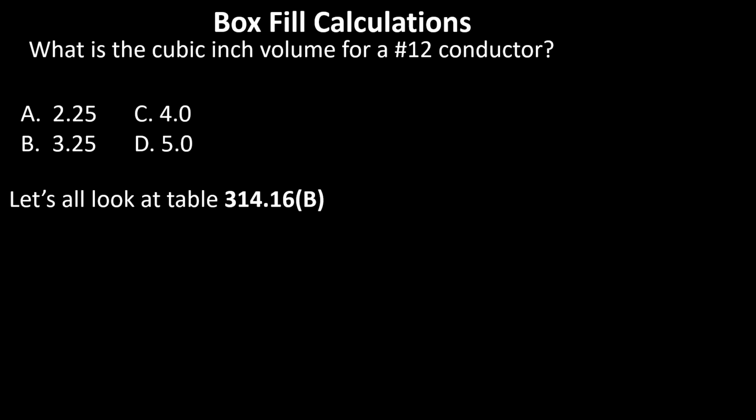So we find a 12-gauge conductor. We use our sheet of paper as a straight edge, and we're going to find that a 12-gauge conductor counts as 2.25 cubic inches as far as box fill volume. Great job.